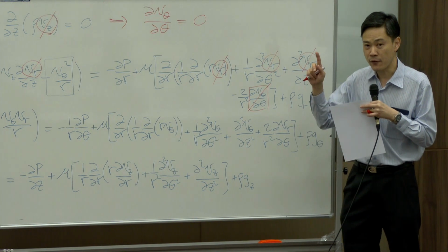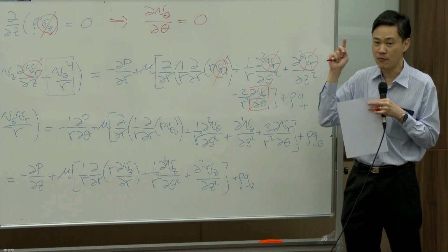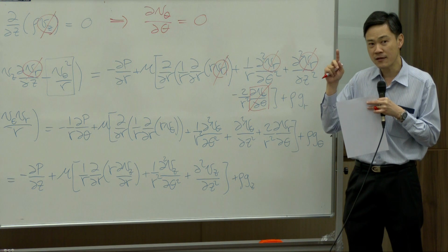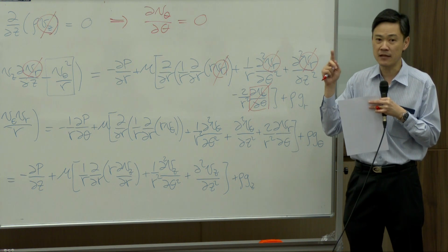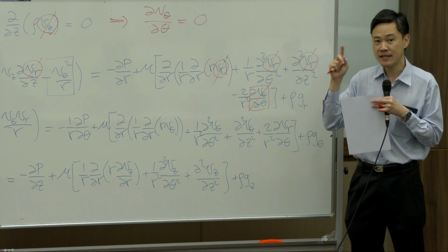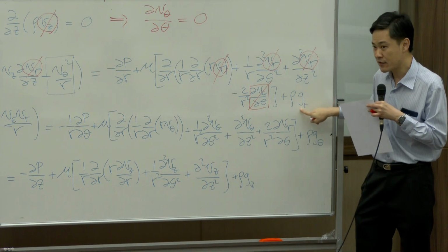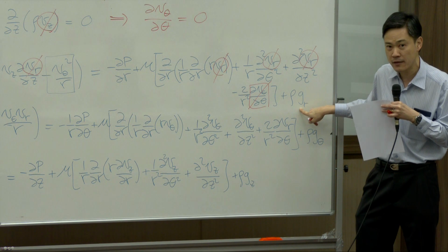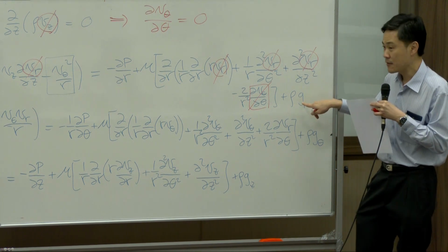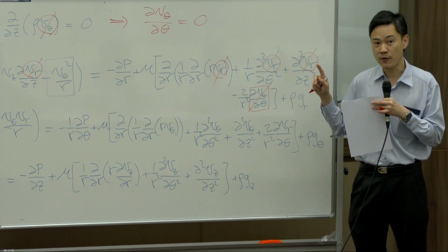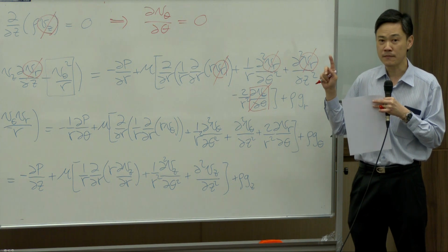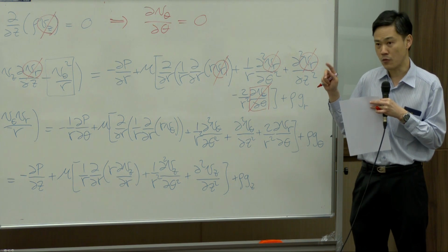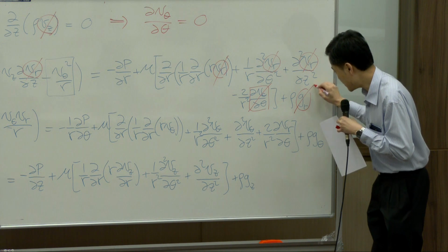If you think carefully, whatever you have in your mind about centrifugal force depends on rotation speed, right? So that depends on the fluid. But this term is supposed to be external force independent from the fluid. So, is there any external force in R direction? No, there is not. So this term is 0.